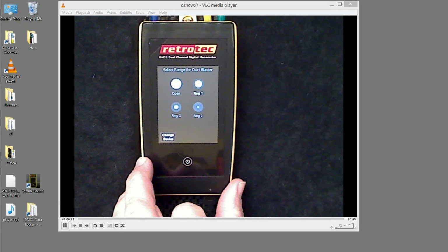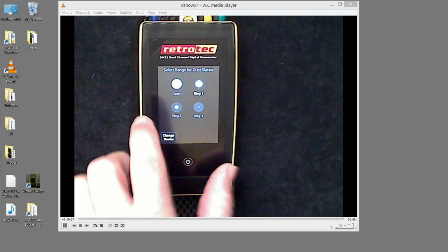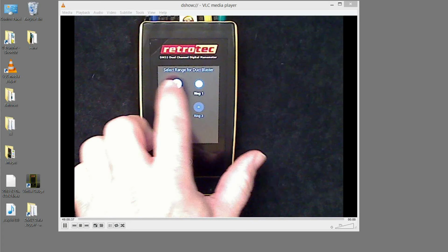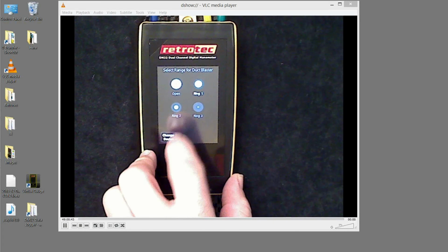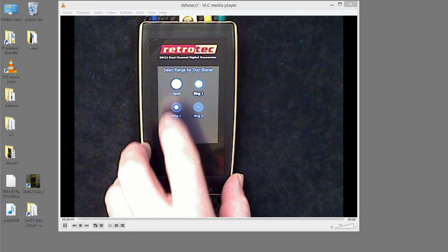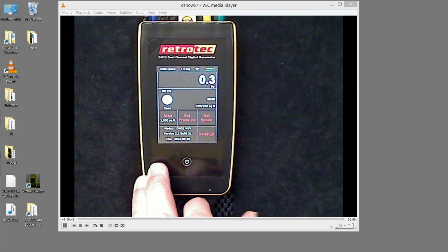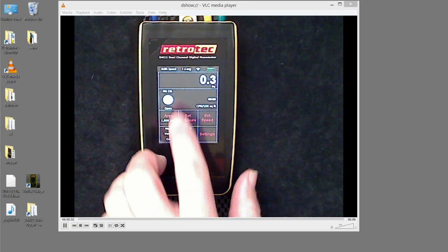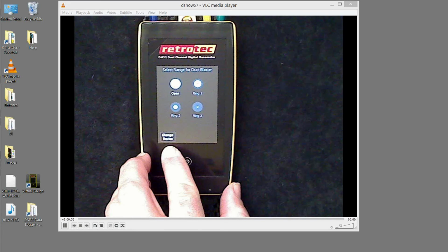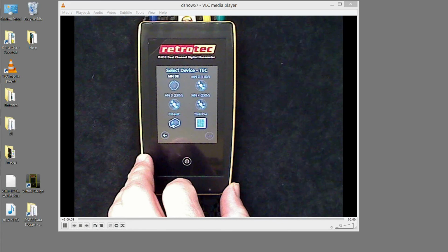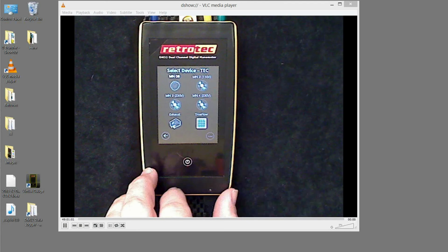These are the ranges for the fan that I have, and it is the Duct Blaster. It tells me at the top, and it tells me which range I want to pick. So I pick a range. If I'm going to leave it open, it goes back and is already set to be open. If I want to change devices, at the bottom I can change device. These are all the Minneapolis Energy Conservatory options and the Duct Blasters I showed before in the slides.